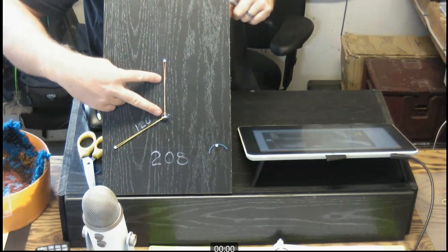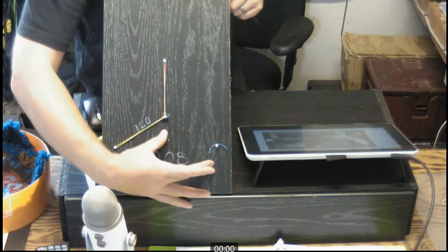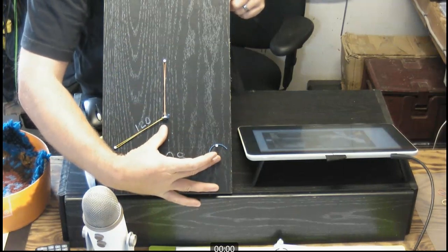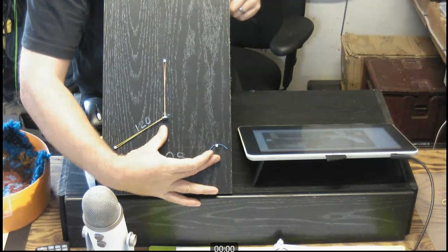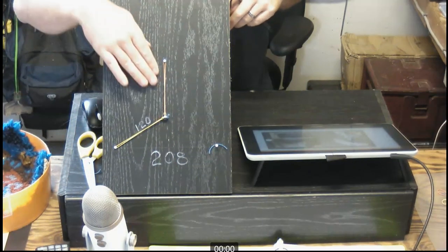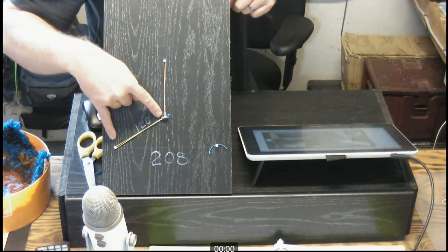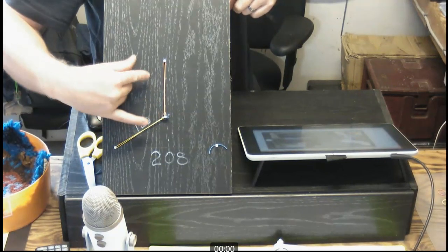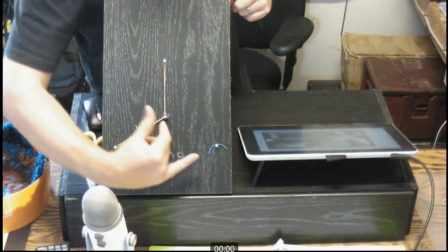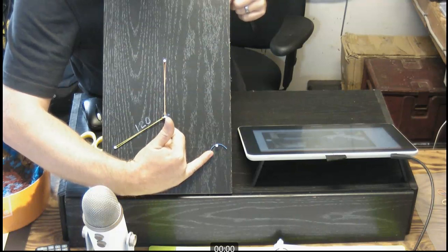This one's going to dissipate full watts. It's still got the proper value of voltage across it. This one over here has got the proper value of voltage across it, but no complete path. So I'm going to have a situation where I get 2/3 of my heat, 2/3 of my elements are working, and I'm going to get full value of voltage, phase voltage, across each of my windings. This one here is going to have a full value of voltage across it, but it does not have current going through it.